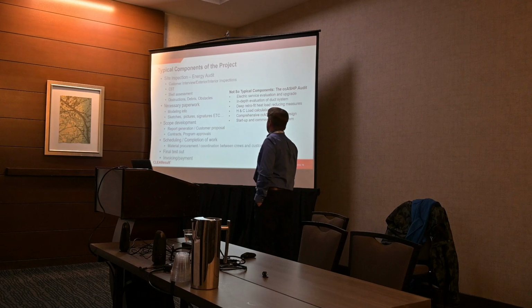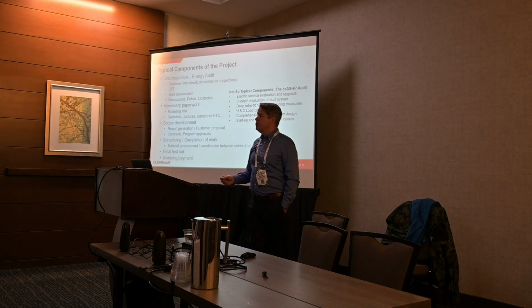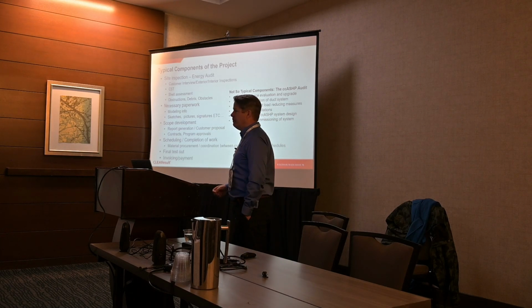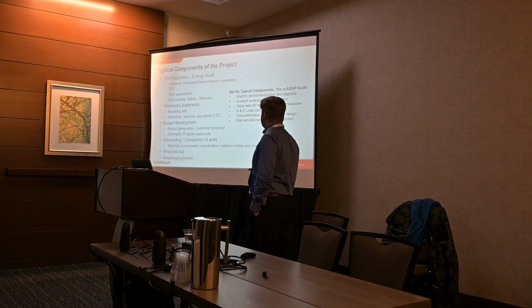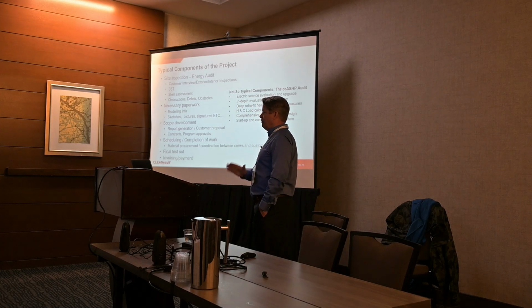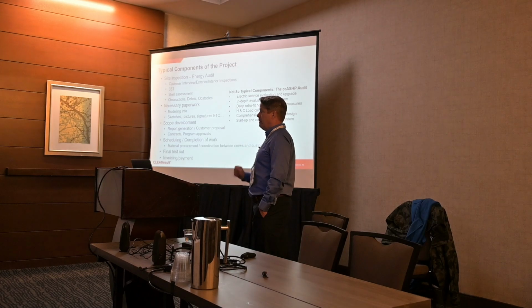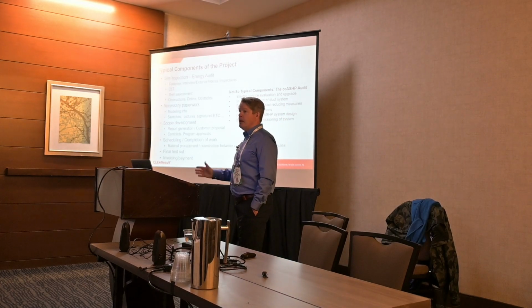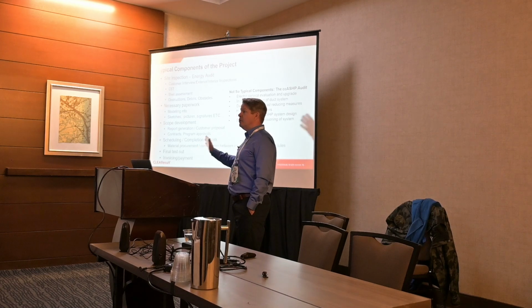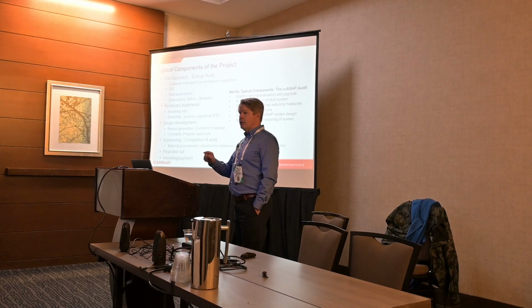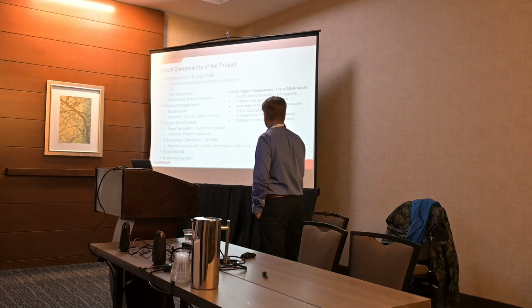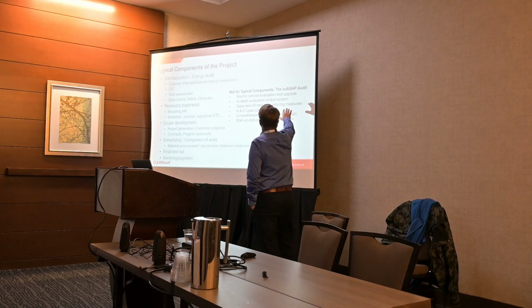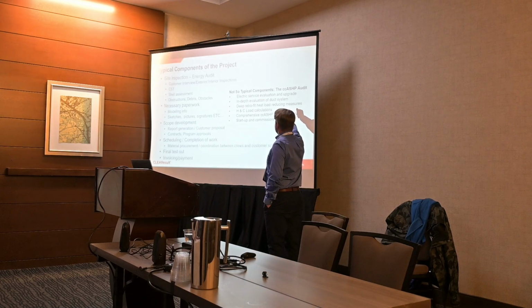Deep retrofit heat load reducing measures. We may want to consider doing things we never considered doing before, right? I know that in the Massachusetts program, they're adamant we don't do spray foam, period, okay? They need to start thinking about spray foam, not all over the house, but maybe the band joist, right? Get the band joist nice and tight, with targeted spray foam, different things like that. So we need to think about load reducing measures we haven't thought about before.